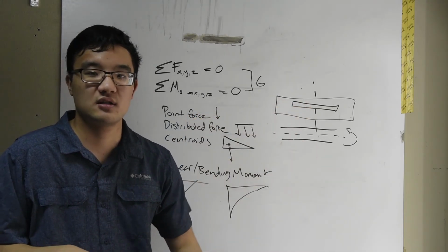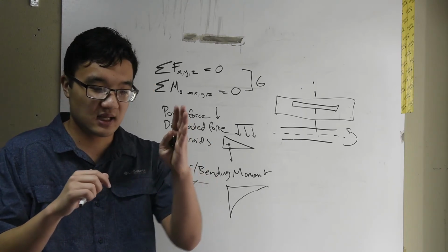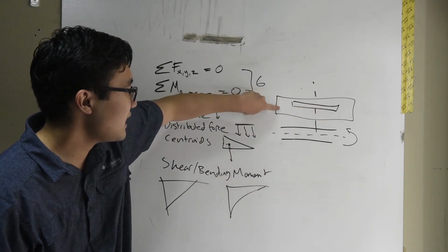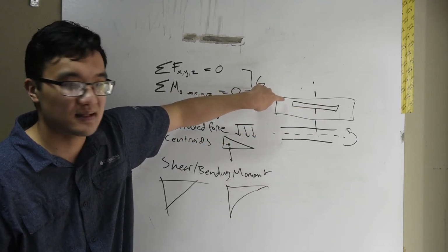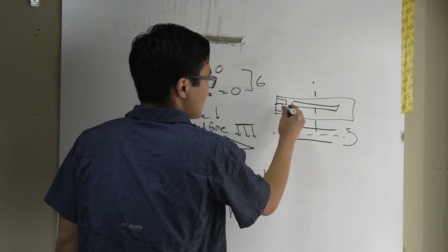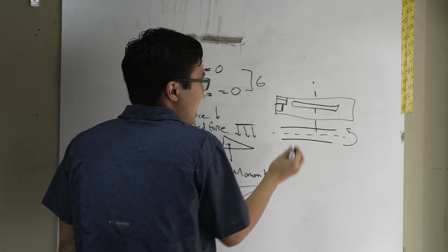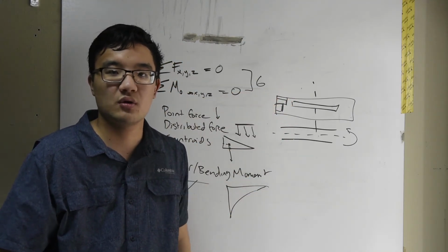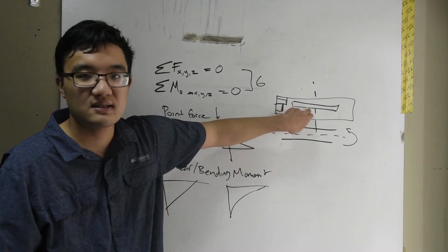We don't want discontinuities. We don't want any seams, any cuts. We need that to be as strong as possible. We don't really care out here because this is not supporting the load. So I can have a bunch of different smaller pieces. It doesn't matter. I don't care about these little cracks because they're out near the tip where there's basically no load applied. But in here, it needs to be strong.